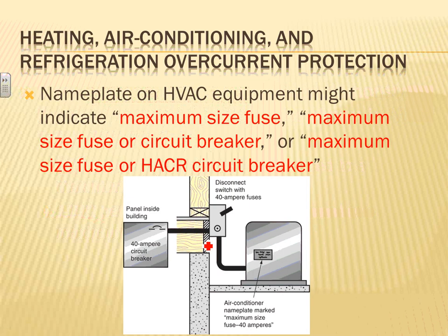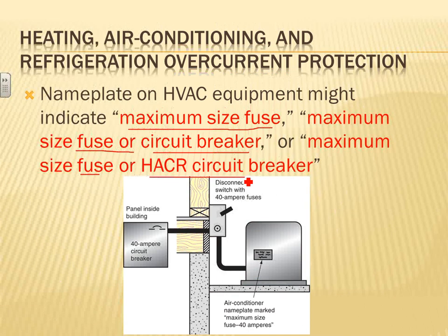Okay, this one is about HVAC equipment. And we'll talk about HVAC equipment, guys. HVAC equipment has to be labeled with either maximum fuse or maximum circuit breaker, or maximum fuse or circuit breaker. So that's when you get into your circuit breaker. If it's used in any piece of equipment that has a compressor in it, refrigeration, anything that has a compressor in it, if it says fuse, you give it a fuse. If it says circuit breaker, give it a circuit breaker. If it says fuse or circuit breaker, then it doesn't matter.